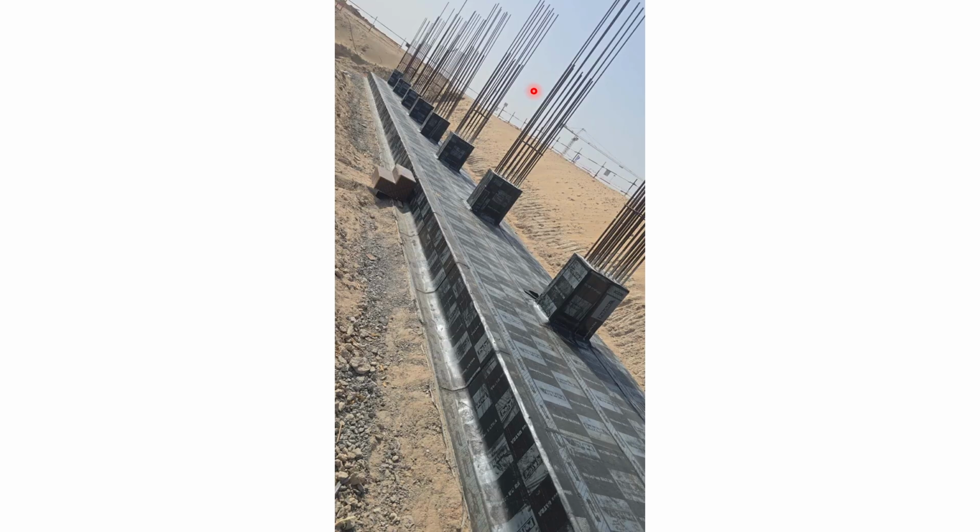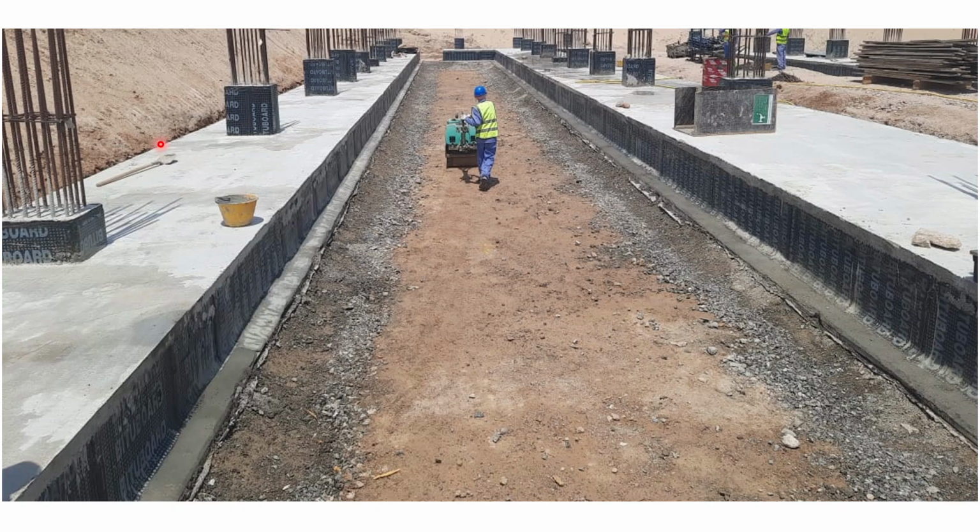You can see the picture from the side also. Like this, you can see this is the membrane. Now this is the horizontal area, this is the vertical area. In this area we need to provide the protection board. In this area we need to provide the screed. So in this picture you can see at the top we provide the screed, and this area is a protection board, and this horizontal area is also protected with screed or mortar of enough thickness, to protect against damage or puncturing of the waterproofing membrane during backfilling work in this area. So these are some very important points from the site that we need to take care of during construction activities.